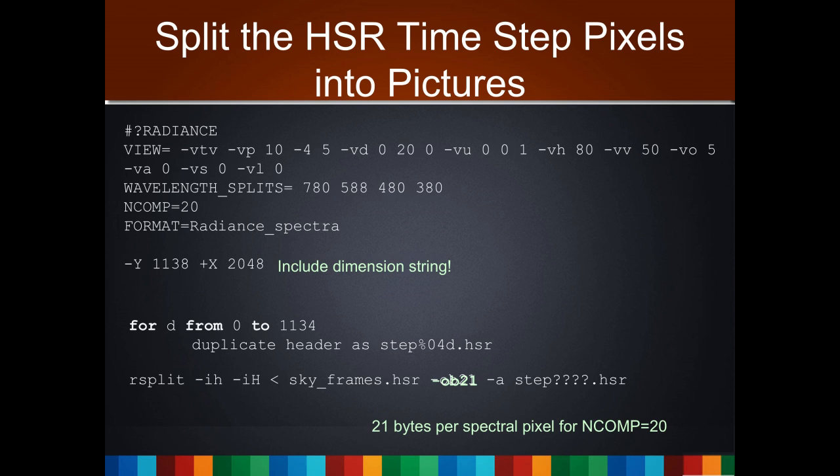The header info that you read with getinfo is just any lines up to the first empty line. That is the definition of the end of the header in Radiance. And then in image files, there's an additional resolution string, which tells the columns and their ordering. So that's what this line is.